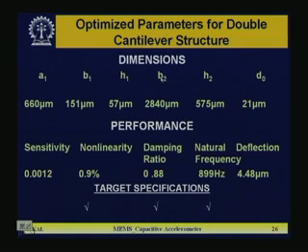B2 and A2 are the same because we are using a square structure, 2840, and H2 is 575 micrometer, that is the substrate thickness of the seismic mass, but the flexure is only 57 micron thick. That has been etched by bulk micromachining, restricted to 57 micrometer.